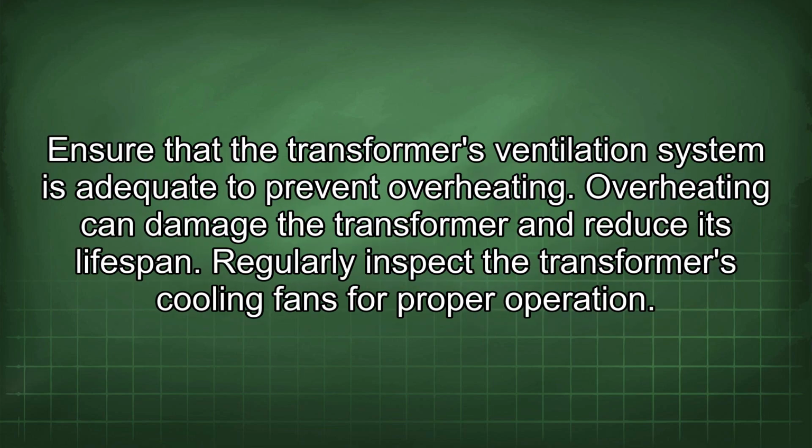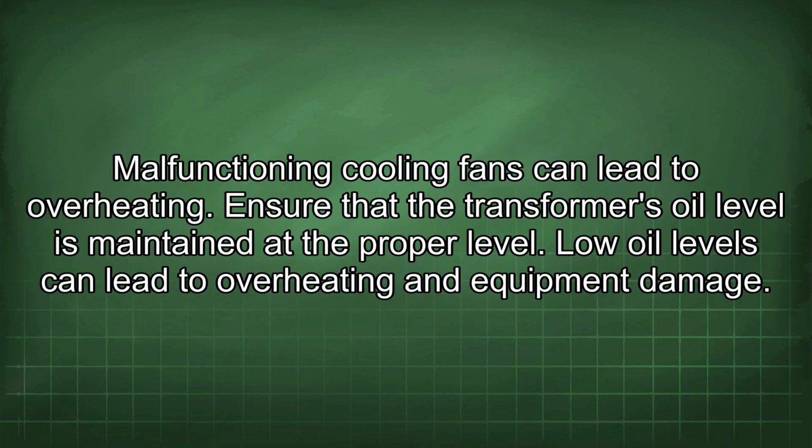Ensure that the transformer's ventilation system is adequate to prevent overheating. Overheating can damage the transformer and reduce its lifespan. Regularly inspect the transformer's cooling fans for proper operation. Malfunctioning cooling fans can lead to overheating.